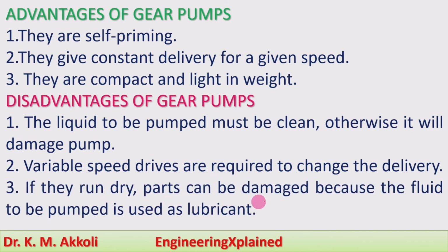If they run dry, parts can be damaged because the fluid being pumped is used as a lubricant. These pumps should not be run dry, otherwise friction will take place between the gears and cause damage, because the fluid works as a lubricant during operation.